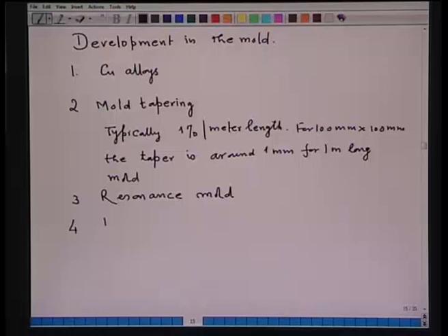So, the property of the meniscus is important, and the height of the molten steel is also important. So, in all modern continuous casters, mold steel level control is put in place, and the steel height in the mold is constantly recorded and maintained at a particular height.